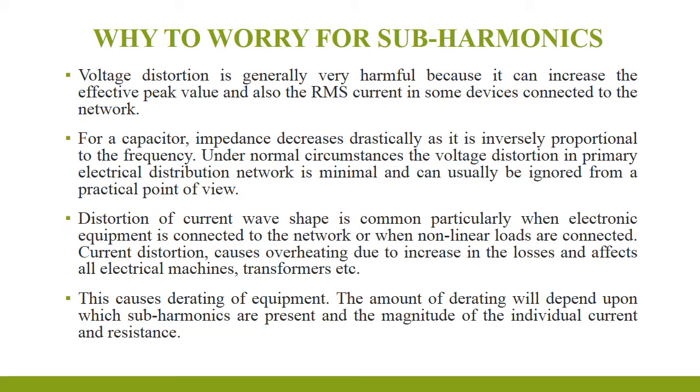Why worry about subharmonics? Voltage distortion is generally very harmful because it can increase the effective peak value and also the RMS current in some devices connected to the network. For a capacitor, impedance decreases drastically as it is inversely proportional to the frequency.